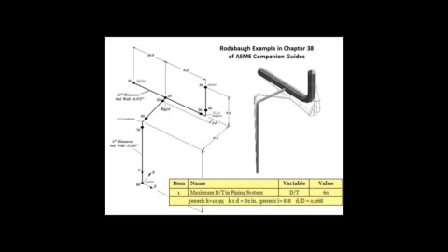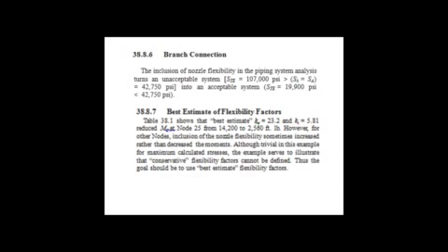The branch runs are 9 foot 9 inches. So we've got 82 inches over 117 inches, which is about 70%. So of the flexibility in the Y direction for the branch, the flexibility gives us a significant contributor to the overall length of the system by the effective length of the flexibility of the branch.